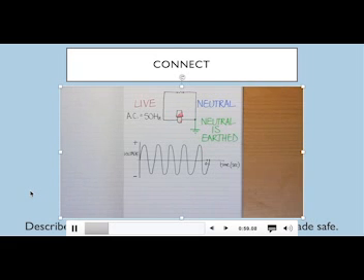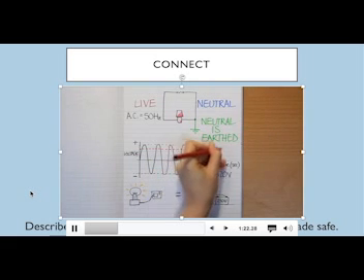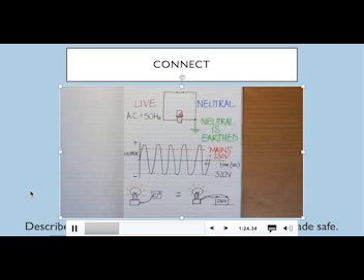Slightly confusingly, the peak potential difference of the mains supply is actually about 320 volts. But because the voltage is alternating, most of the time it's below this peak value, meaning that when you connect it to a resistor or a light bulb, these behave as if they're actually attached to a 230 volt battery. So to make things a bit easier, we normally talk about the mains being 230 volts.